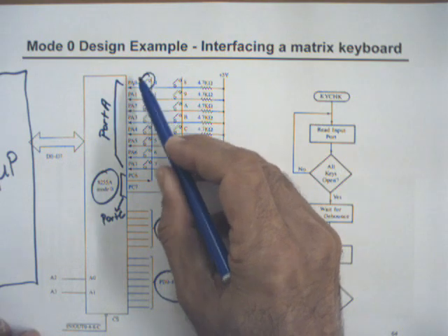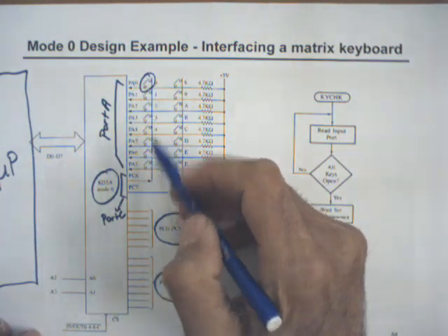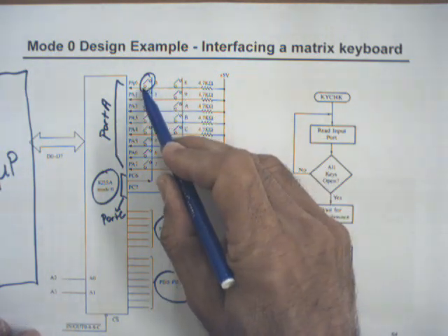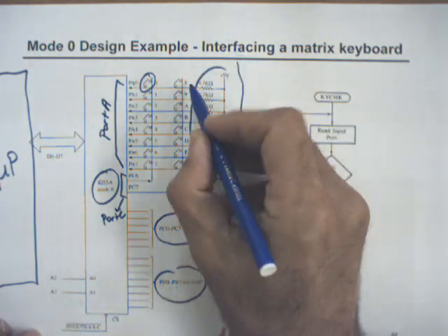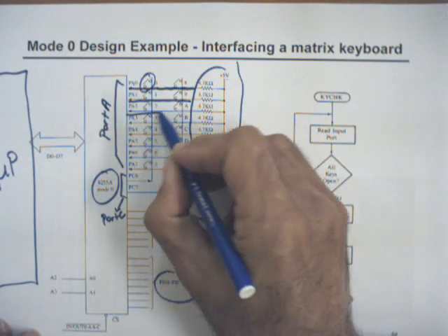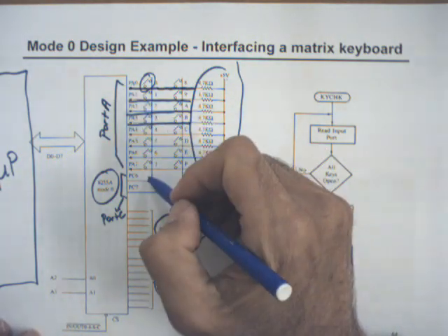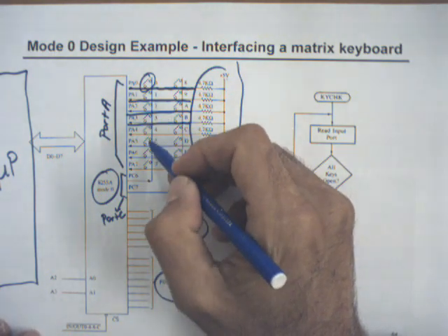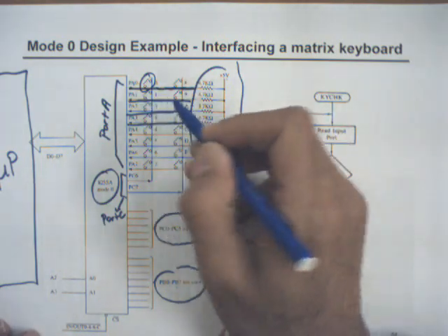Whenever you press a push button, you connect a logic level of high through this resistor, and this line is always high. You can draw this line to low, and if this detects high, then that means this key press is released.